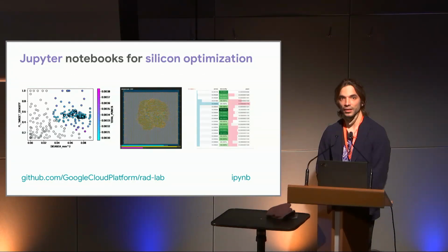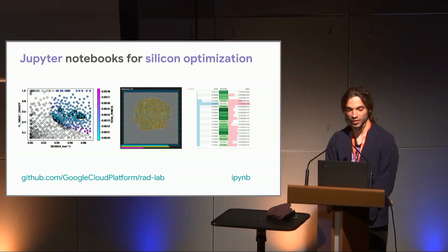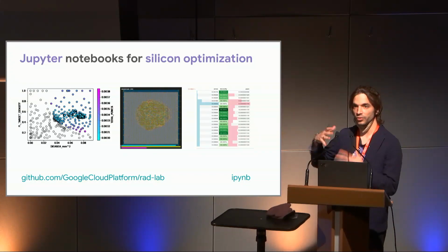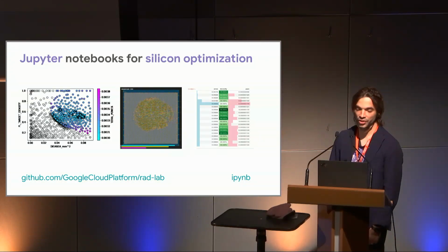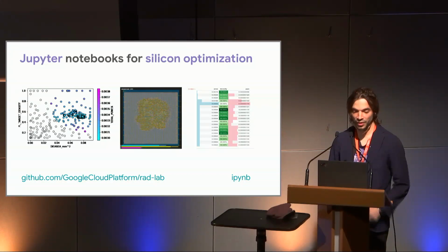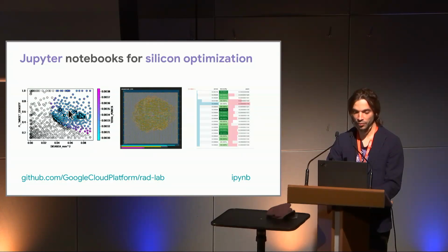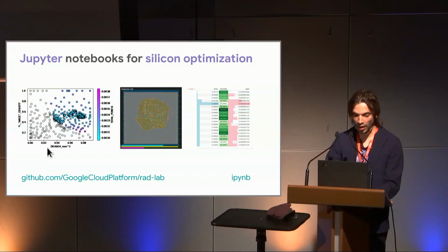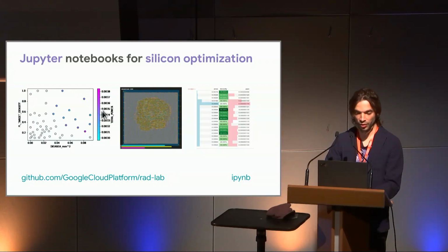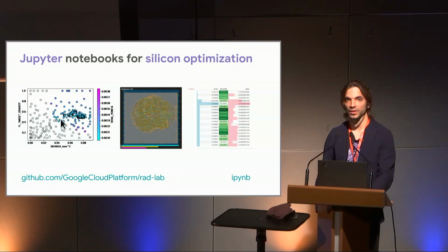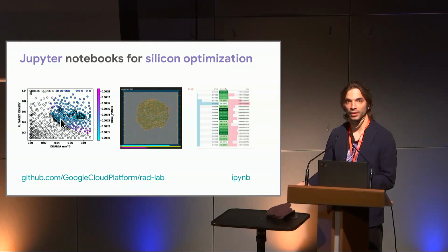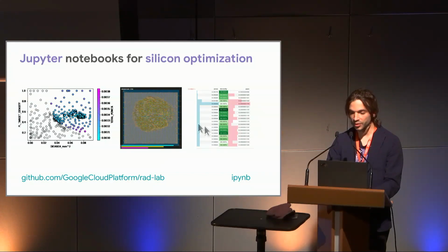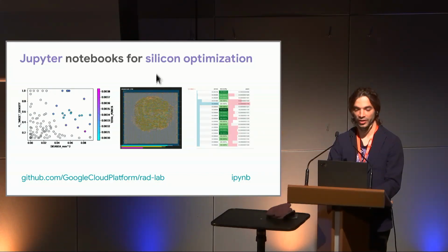Another aspect of this is doing optimization using notebooks. Because I'm working at Google, we also have a platform called Google Cloud, and we were able to run a lot of parameterized job exploration to try to optimize notebooks. And so you can see here on the left, I'm running jobs to try to optimize the area and the density of a given chip and trying to minimize power. Each of those dots that you see here is a notebook that I can run with different parameters, and I can extract the different layers that got produced there, and extract the data as well, and analyze it with Pandas.